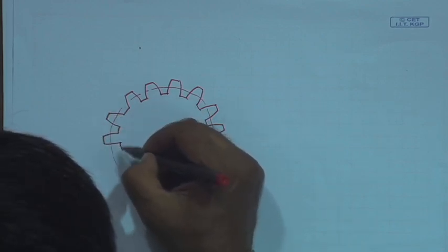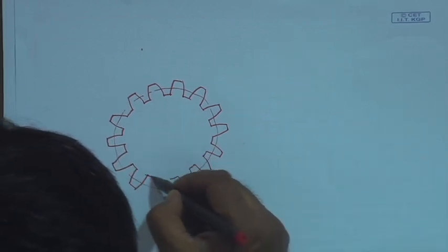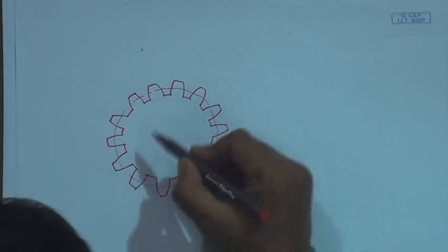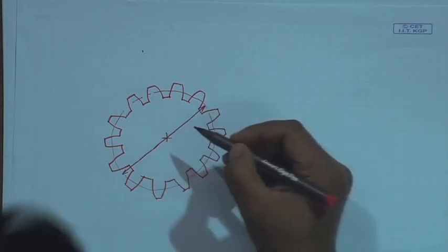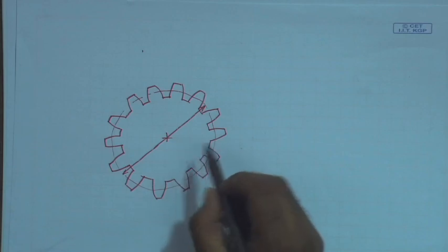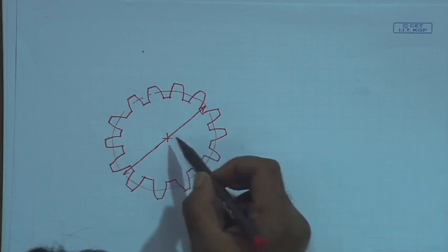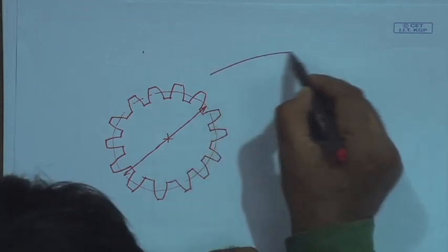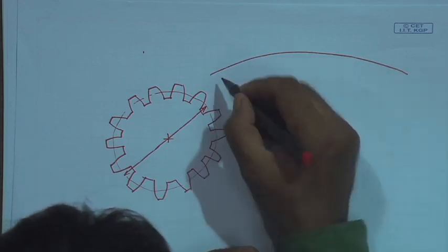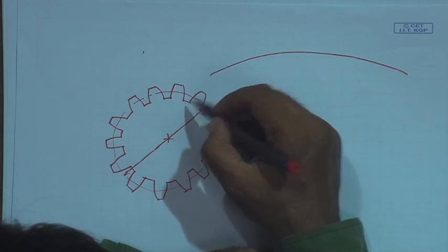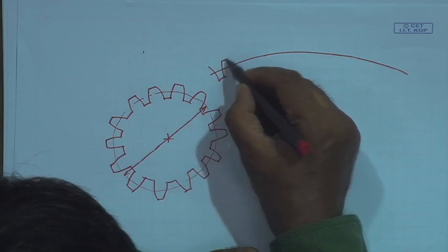If the gear teeth are of the same size, as we go on increasing the dimensions of a gear, that means if I increase this particular diameter, this is referred to as the pitch diameter, I will be getting proportionally higher number of teeth. Now, you might say, is that really necessary? If I have a large diameter, of course, I cannot draw it fully here. Does it mean that proportionately, for it to mesh with this one, it has to have more number of teeth? Yes, essentially so.